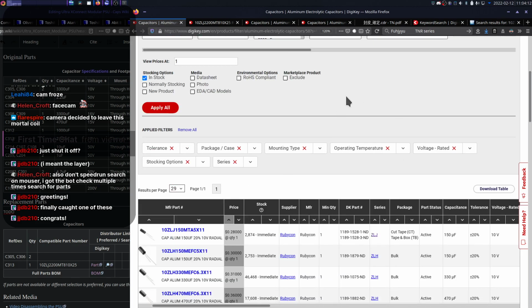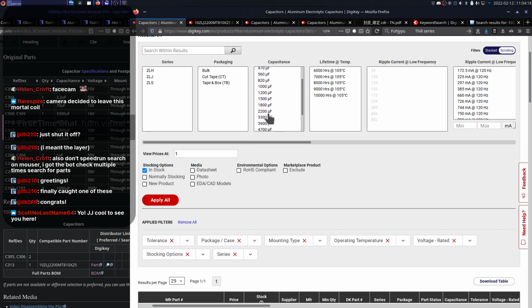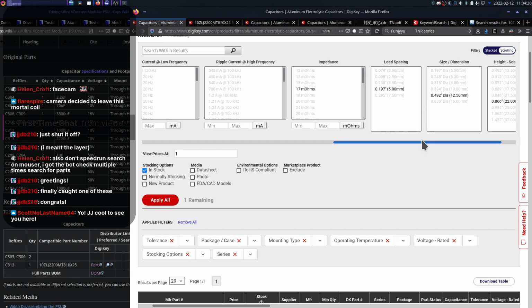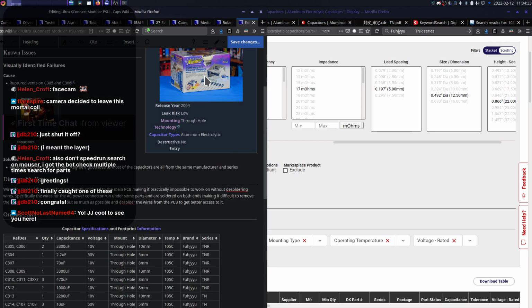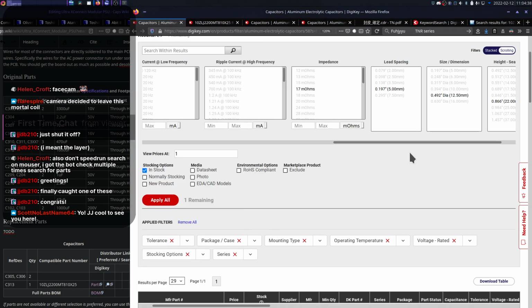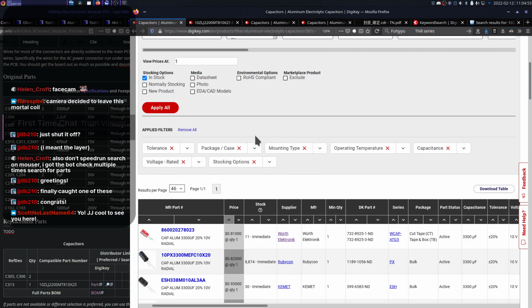So, yeah, all right. I filtered out. I need to select capacitor for 3300 µF. Let's do that. And then, oh man, what diameter is it? It is 12. These are packed in like sardines in there, so I really don't think I can futz the diameter. So I'm going to have to pick a different capacitor series. All right, we'll nix that. Did it apply capacitance there?